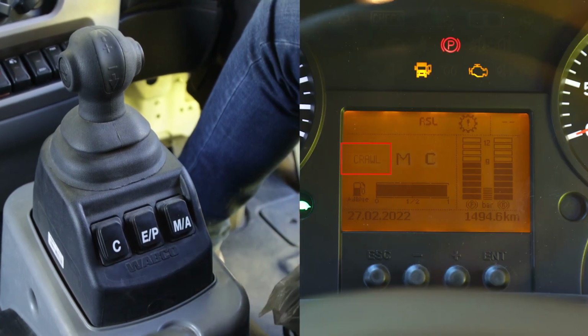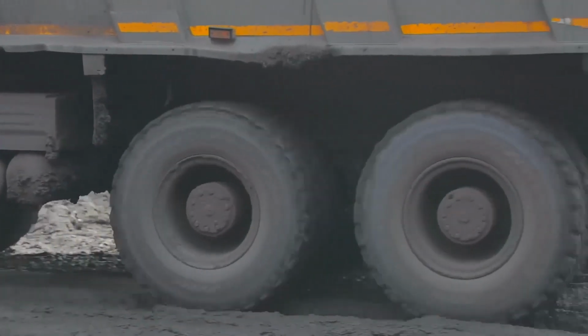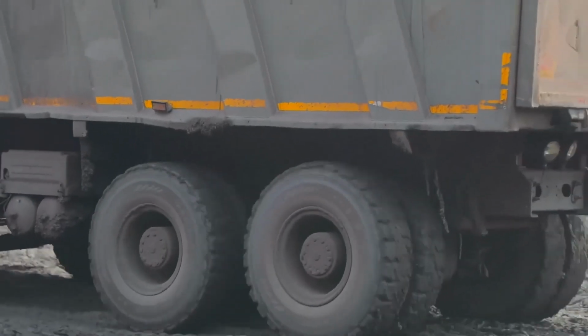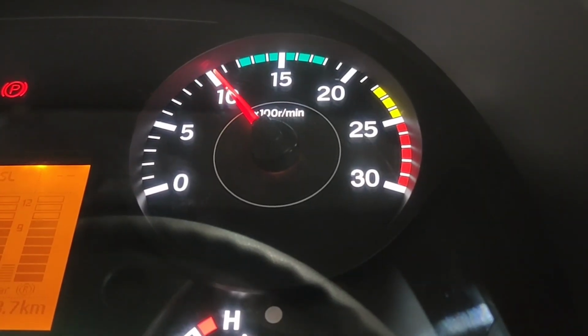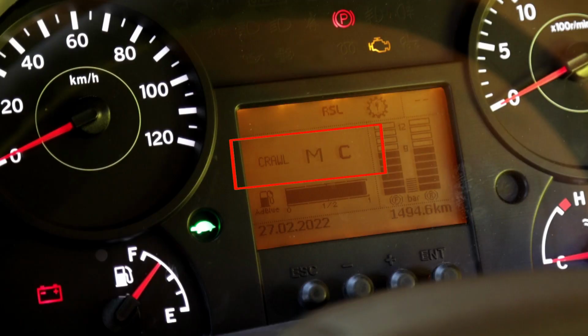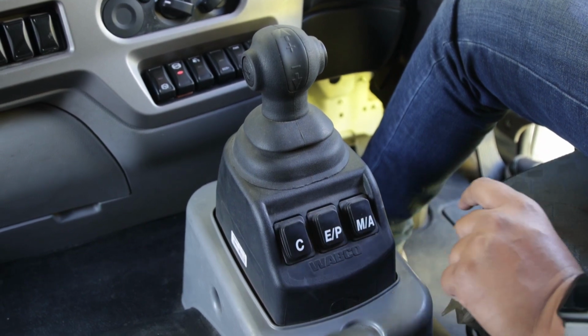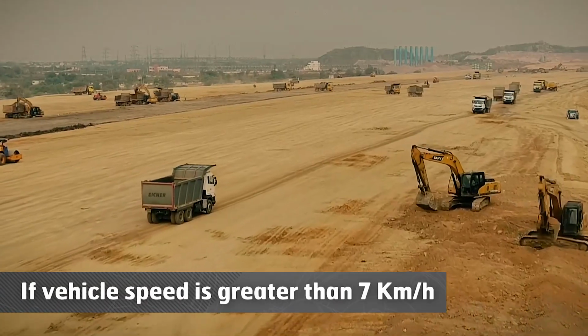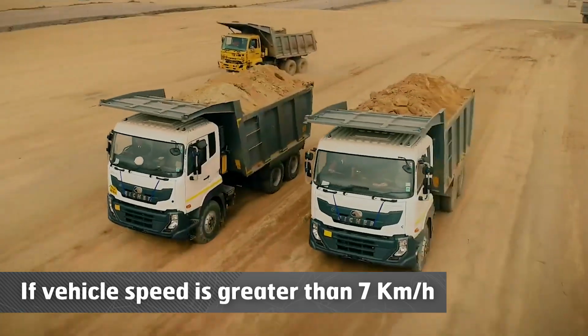In crawler mode, the shift lever unit assists vehicle launching in extreme conditions like soft and muddy roads or on a gradient. It requests higher engine speed compared to normal launching. In crawler mode, only crawler gear and reverse gear will be activated. Crawler mode can be disabled by pressing the C button again, or it is automatically disabled if vehicle speed is greater than 7 km per hour.